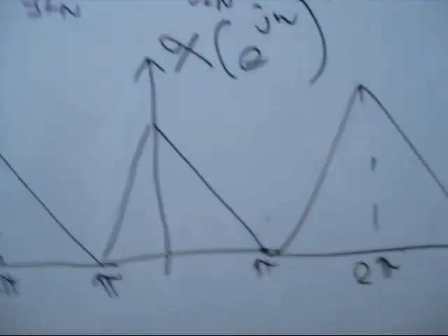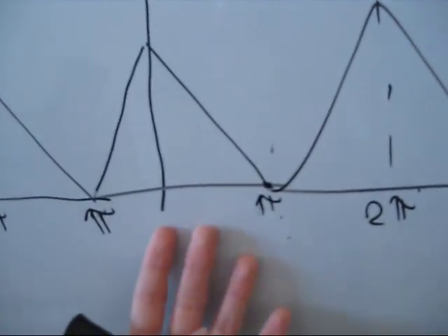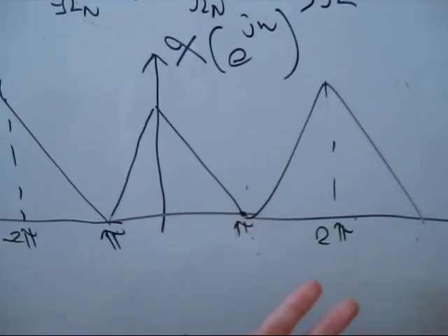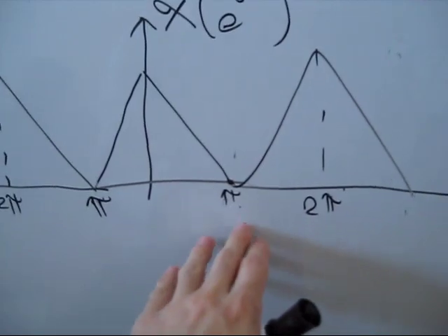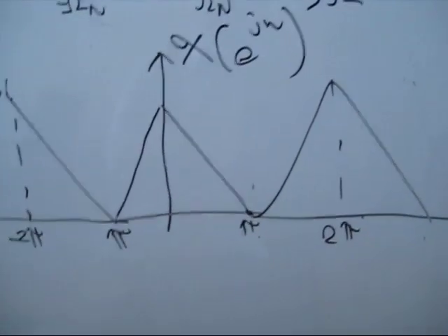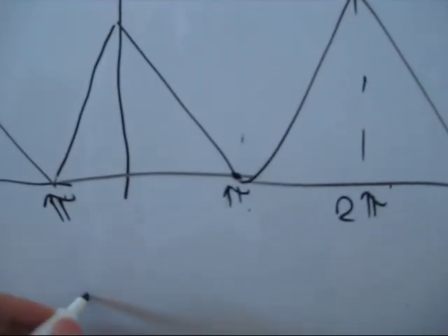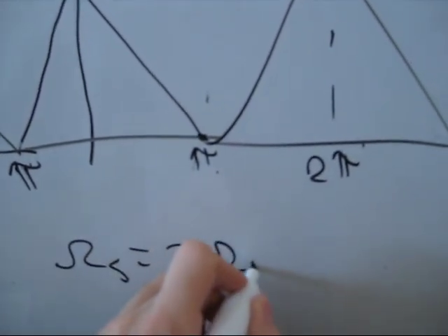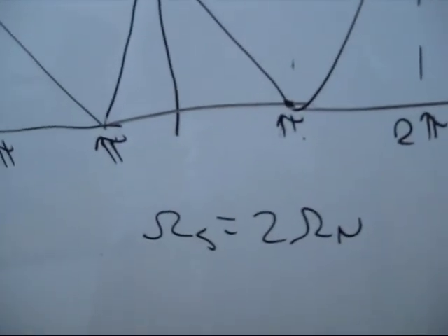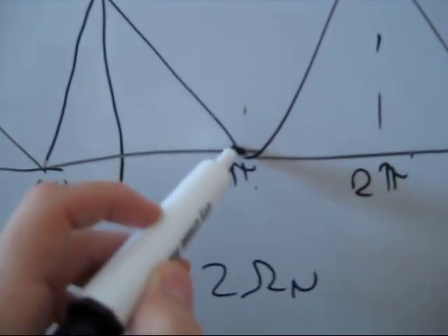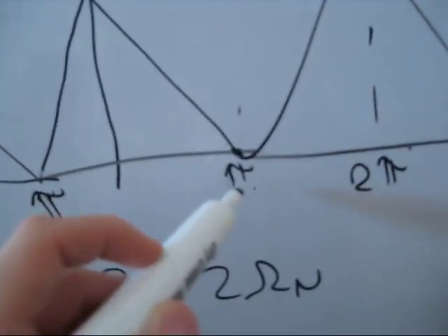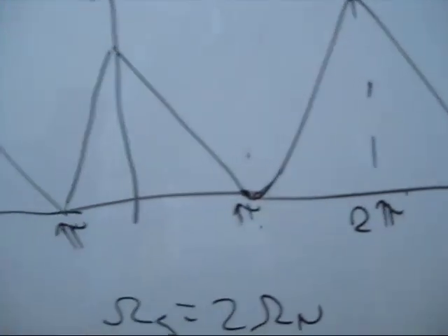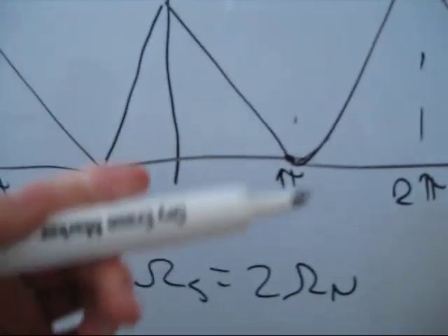So what does that mean? Well, if you look at this, it shows that what you've got is the signal that you would have gotten if you had originally just sampled at only 2 times the Nyquist frequency. Because, as you can see, barring my poor drawing skills, they just touch and they don't introduce any aliasing.